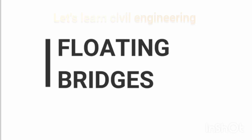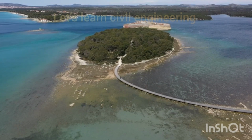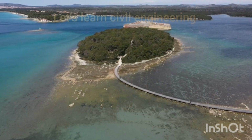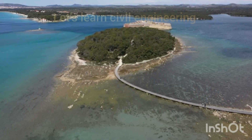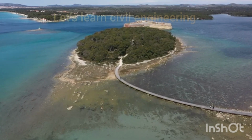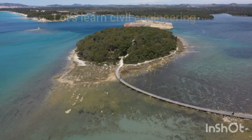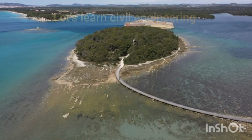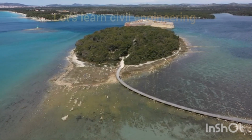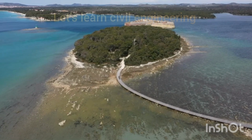Floating bridges. Floating bridges are cost-effective solutions for crossing a large body of water with unusual depth and very soft bottom where conventional piers are impractical. For a site where the water is 2 to 5 kilometers wide, 30 to 60 m deep, and a very soft bottom extending another 30 to 60 m, a floating bridge is estimated to cost 3 to 5 times less than a long-span fixed bridge, tube, or tunnel.